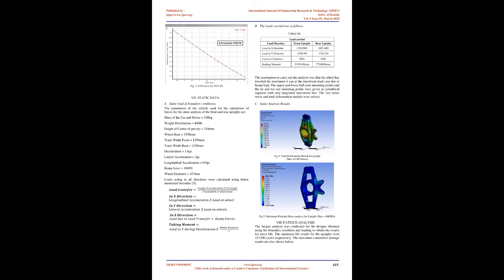5. CAD model of the design. The uprights were designed using the 3D modeling software SOLIDWORKS. With the past year's designs, experiences, and requirements, various designs were prepared to obtain a design shown below on the basis of the results obtained on static analysis for von Mises stress, stress flow and maximum deformation. The uprights designed are required to have a high stiffness and light weight to resist the camber changes in the wheel assembly.